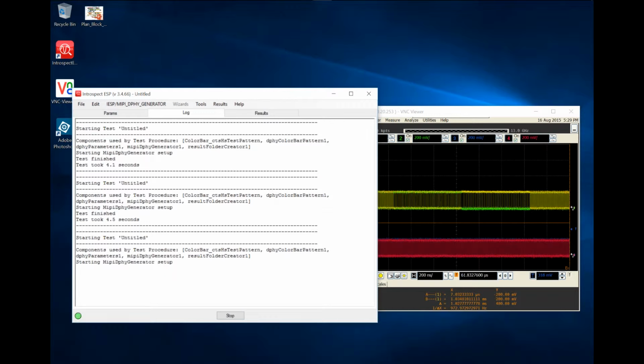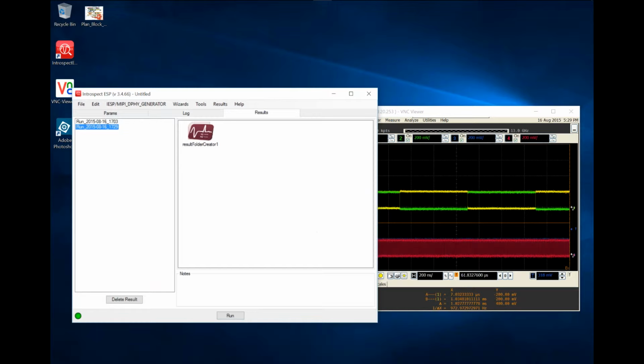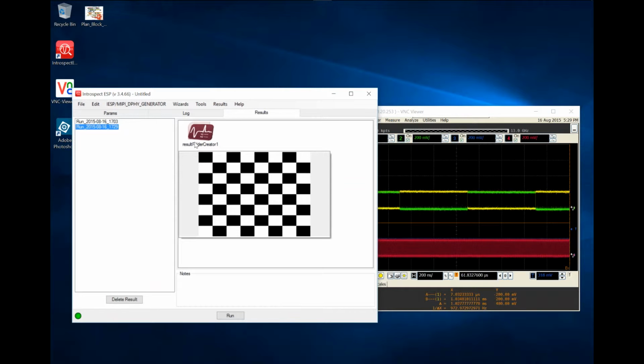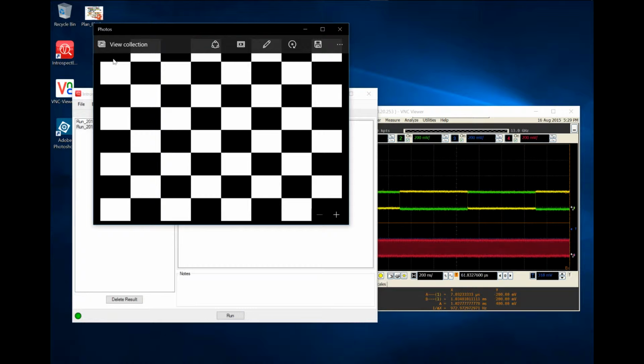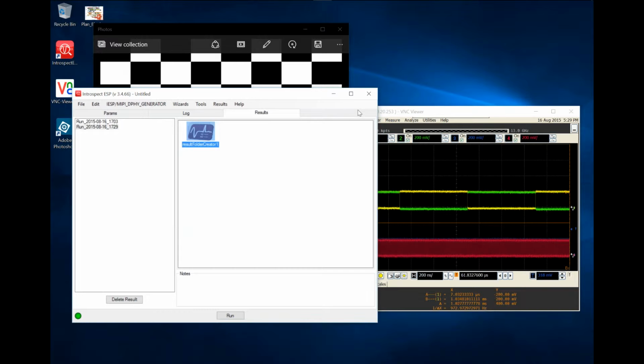a couple of things happen when I click run. One is the tool gives me a preview of the pattern that it generated, and as you can see, if I hover my mouse over it here, I already see the preview. I could open it and basically see that we've created alternating 0, black and white positions in the image. There is 8 of them across the horizontal axis here, and 8 of them across the vertical axis, exactly the way I asked. And so the tool gave me a preview of what I created just to make sure that it was fine, but certainly also